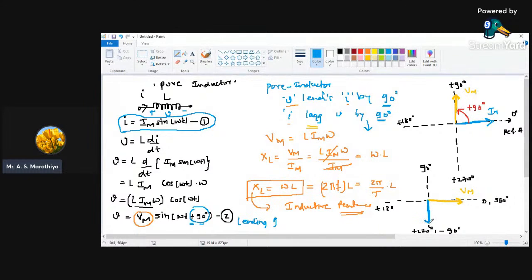So this is going to be Im, and from here it is very clear that the current is going to lag the voltage by an angle of 90 degree. That's why we need to indicate them in clockwise. Now I think it is very clear why we need to take the leading quantity in the anti-clockwise and why we need to take the lagging quantity in the clockwise.